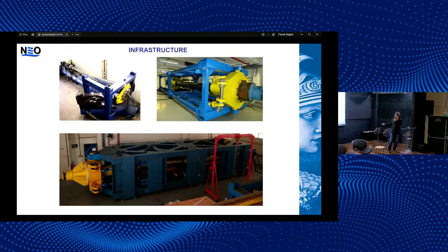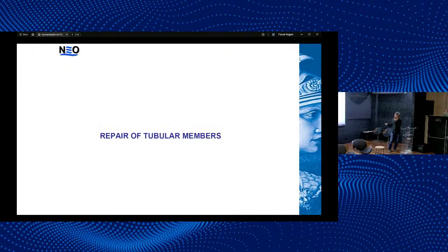In the bottom of the presentation slide, we have a rig of very high capacity, 500 tons, where we can test a flexible pipe with the bend stiffener and simulate the top connection. And we have a flexible hyperbaric chamber where we mainly simulate the touchdown point and instability of the tensile armor wires of flexible pipes, subject to external pressure and cyclic curvature.